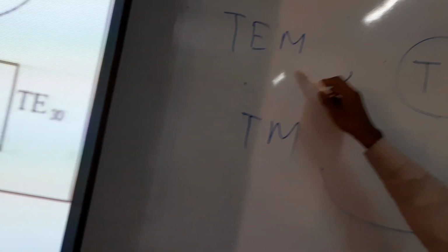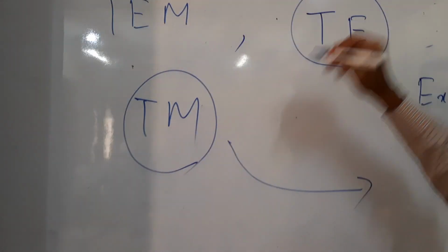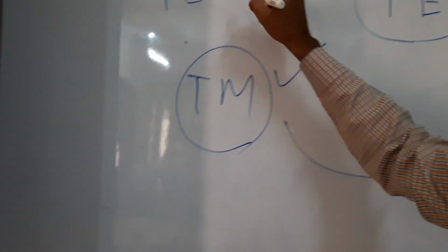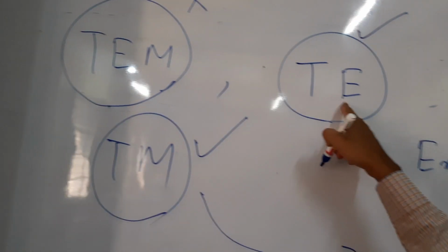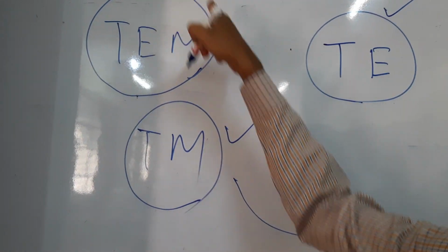So we will study all these things: transverse electromagnetic mode, TE mode, and TM mode. In your waveguide we have this TE mode and TM mode. This waveguide does not support the TEM mode; your waveguide supports TE and TM modes. In the space it propagates.